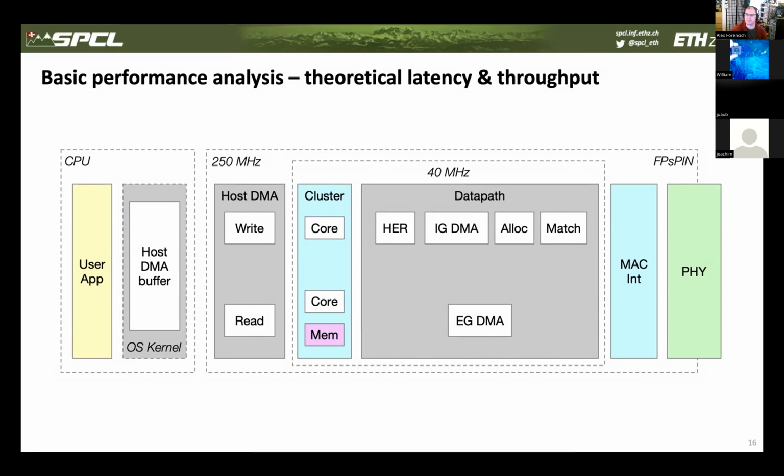That's definitely something we can look into in the future. If I'm going to improve and try to add some level of concurrency, I'm not a professional ASIC or RTL engineer, so this is going to get slower and not be able to run at 250 anymore. I will probably move it in and then CDC the descriptors and response, and use the dual clock RAM interface as you suggested.